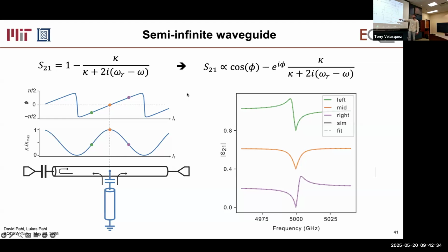Now, the rightwards traveling photons just go to your port and up, and they're part of the information you retrieve. If this capacitance here weren't there, then this other half would be lost. And in fact, this would reduce your collection efficiency or your quantum efficiency. In other words, it would reduce your signal to noise ratio. So often we put a capacitance here such that the photons that couple and go to the left, when they reach here, are reflected back, and this is almost a perfect reflective boundary, and then they also travel to the right. And now you get all of your photons going back up.